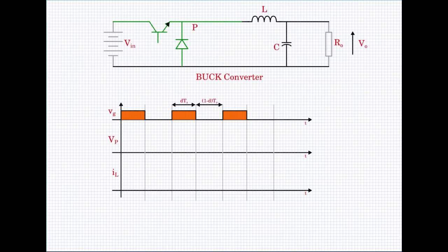So let us mark that. So I am going to place this waveform here. See here that the blue colored waveform is the pole voltage waveform that appears here. During the time when the Q is on, the pole voltage is high and it is the Vin value, and let me indicate it by the symbol Vin.